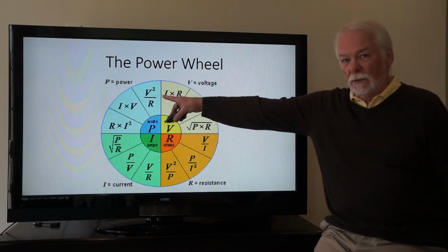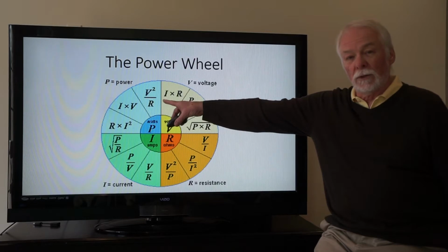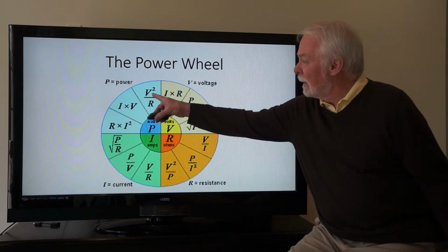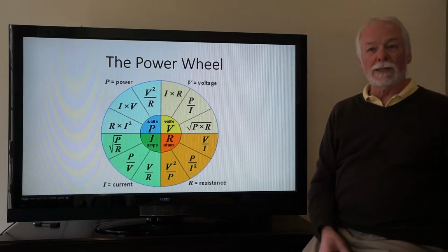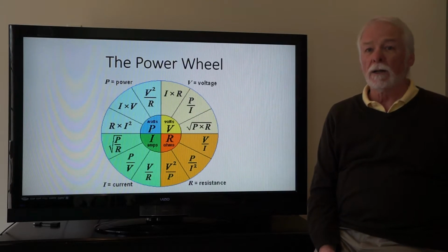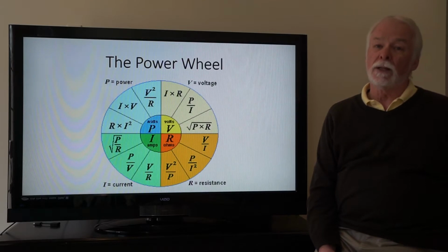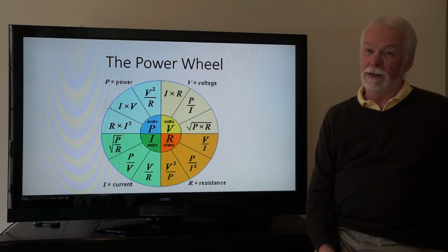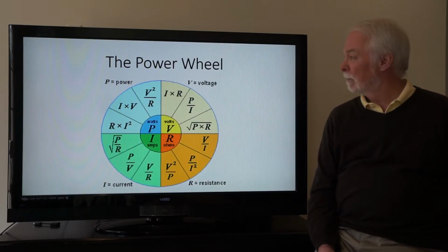We know that the voltage of the 2 light bulbs is the same, 120 volts, right? So that won't matter, and we're left with P is equal to V squared over R, but the important part is that R is inversely proportional to P, meaning the larger the wattage, the smaller the resistance. So we've rather handily answered our question.